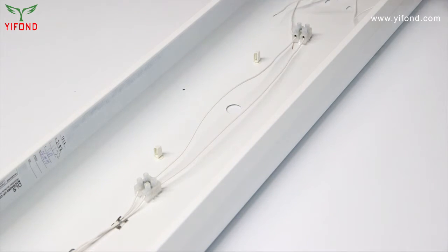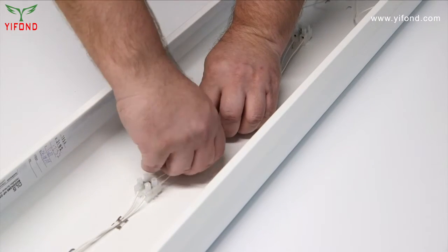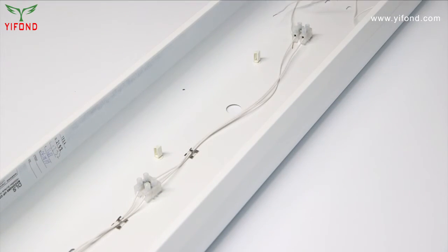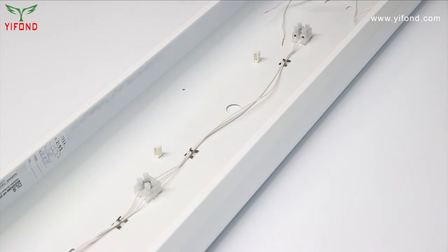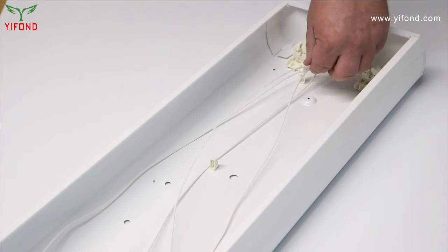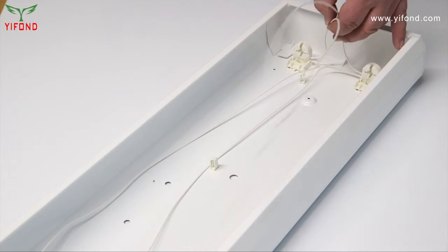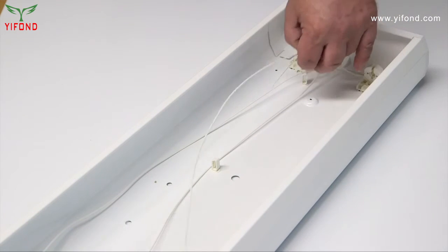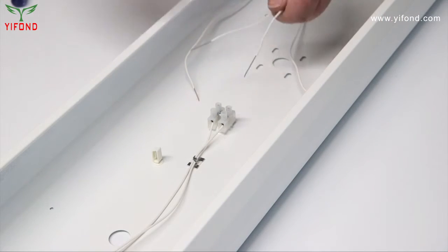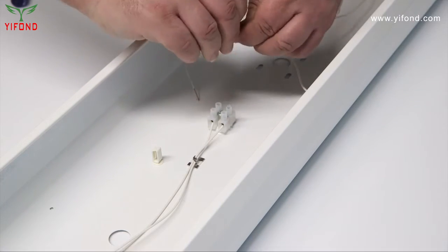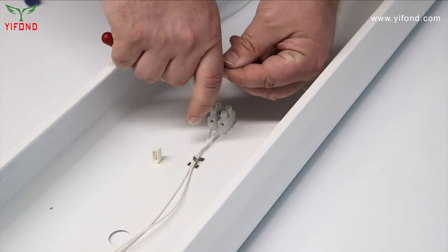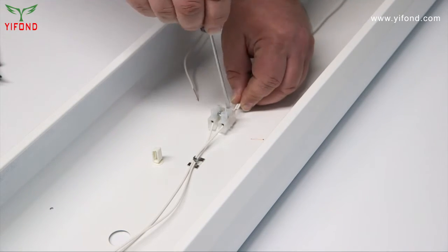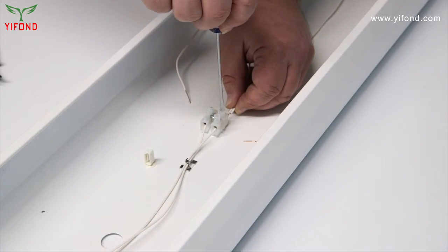It is important to note that when wiring the fitting, the wires are routed in the most efficient way and secured in place. Here we are using some cable clips to secure the wires, which we have stripped beforehand. One wire from each tube connector will serve as the live wires, the other two will be the neutral wires. We have selected the top wire from each connector as the live wire. These live wires are then both secured into one side of the terminal block that then connects to the mains input live.